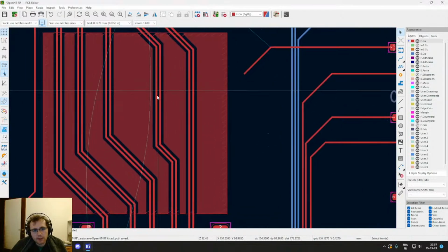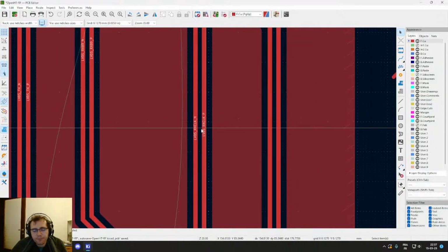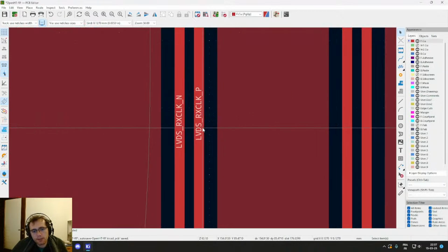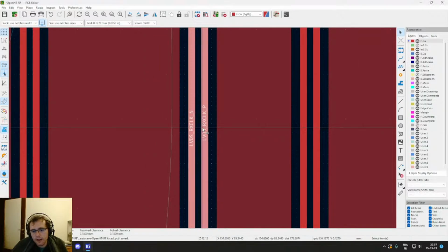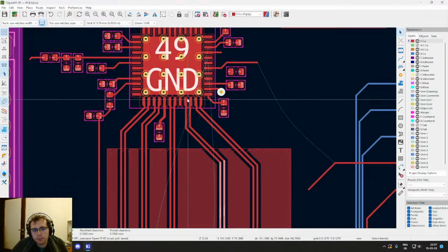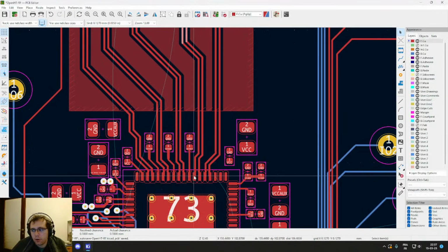Let's say those are LVDS pairs, so the most coupling in the system is in between those two lines. You have to put them close to one another at a specific distance with a specific track width, which means it's gonna be impedance matched from the inside of the transceiver to the inside of the FPGA. It's a 100 ohm differential.